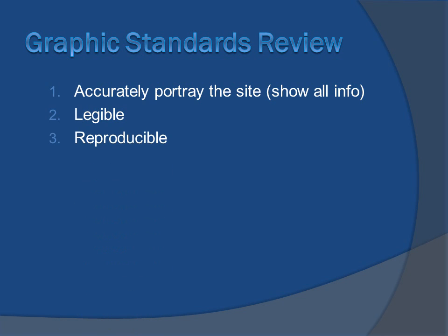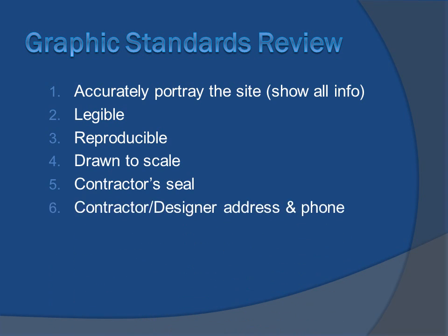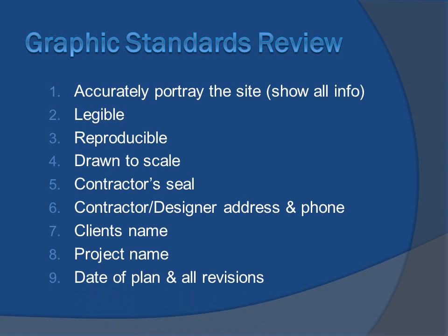Needs to be reproducible. Drawn to scale. Have your seal. Have your address, a way for the client to contact you. The client's name, project name, date of plan and all revisions, and lacking coffee stains.